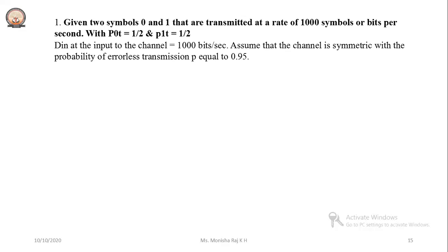However, this is not satisfactory since the receiver does not know exactly which bits are in error, even though it knows that on the average 50 out of 1000 bits are incorrect. The inconsistency in defining information transmitted over a channel as the difference between the input data rate and the error rate can be removed by making use of the information lost in the channel due to the errors.